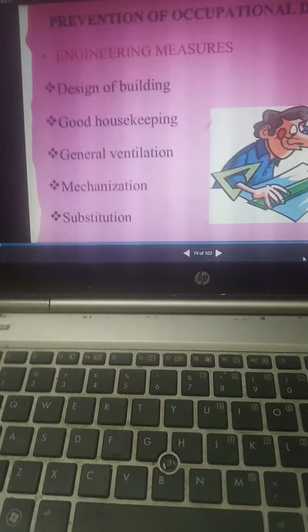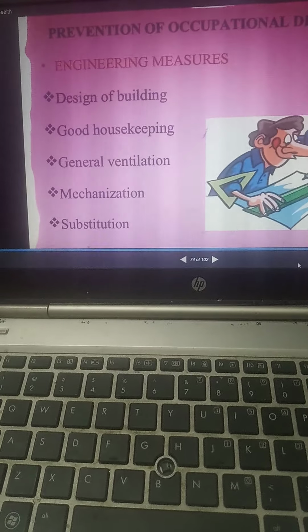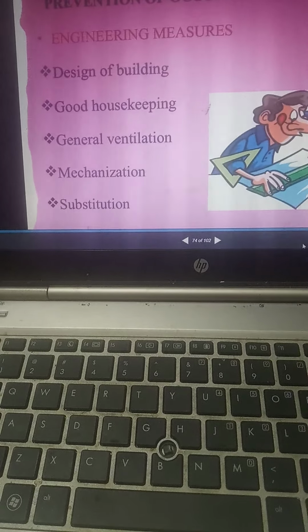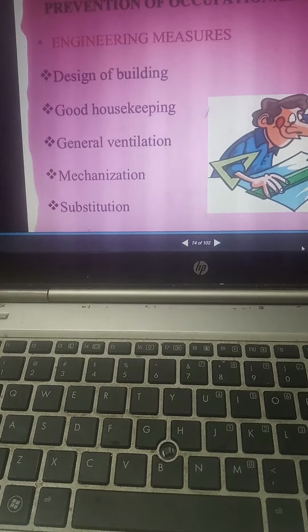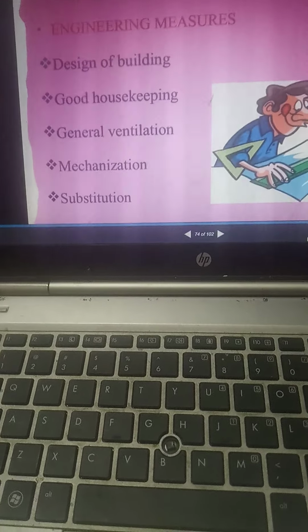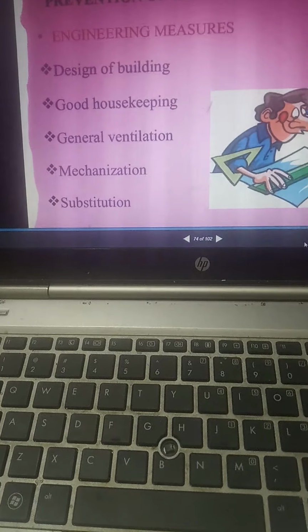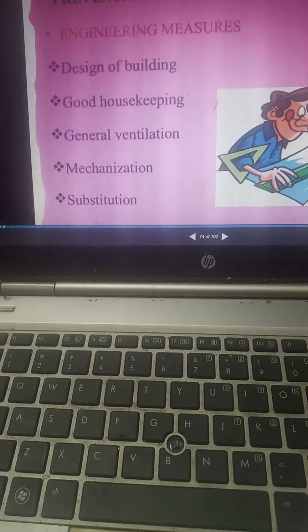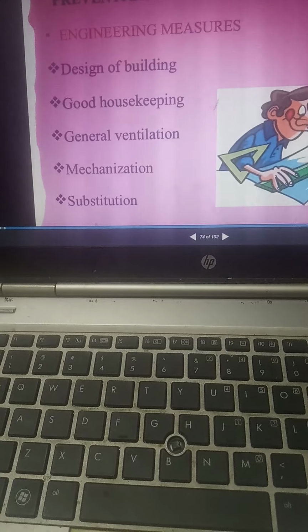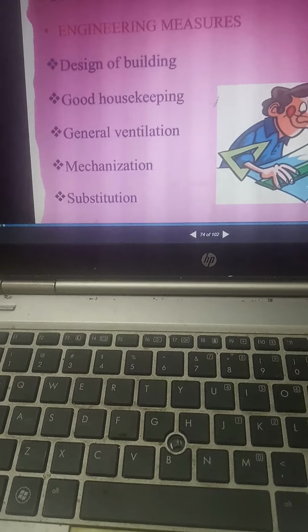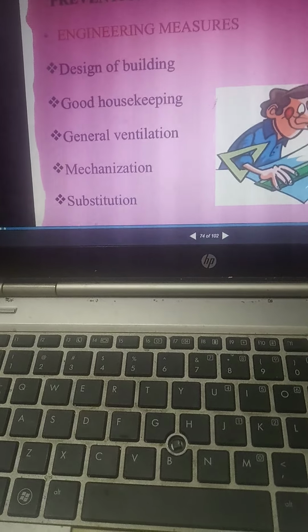General ventilation. There should be good general ventilation in the factory. It has been recommended that in every room of the factory, ventilating openings shall be provided in the proportion of 5 square feet for each worker employed in such a room, and openings shall be such as to admit continued supply of fresh air. In rooms where dust is generated, there should be an efficient exhaust ventilation system. Good general ventilation decreases airborne hazards to the workers, especially hazards from dust and gases. The Indian Factories Act has prescribed a minimum 500 cubic feet of airspace for each worker.